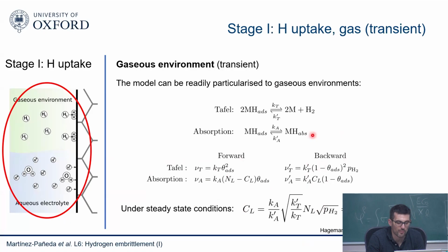So everything seems consistent, you recover that steady state scenario. But the key point is that Sieverts' law works very well for steady state, but if we want to try this idea of the Japanese of putting oxygen in and seeing whether it blocks hydrogen uptake, you need a transient model. This kind of model will be able to capture that.